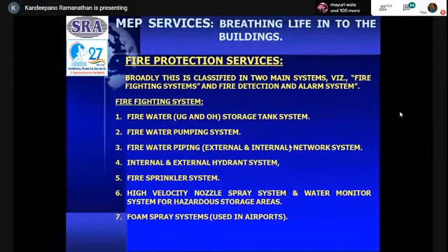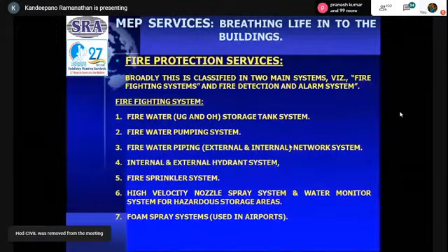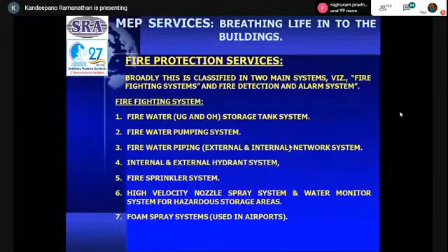Then foam spray systems. Foam spray systems are used for flammable liquid fires like petrol, diesel, etc. In big airports where an aeroplane catches fire, the amount of foam to be discharged has to be huge because the airplane will be 150, 200 feet long.